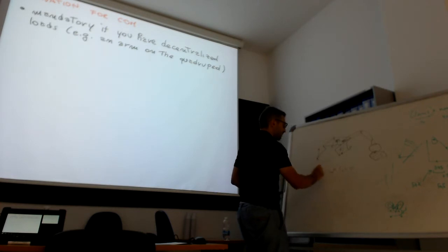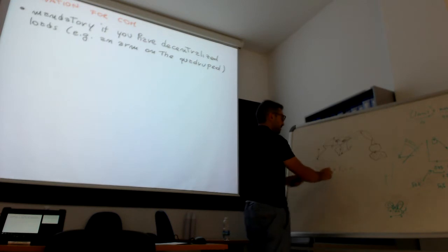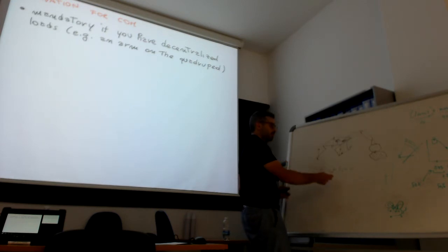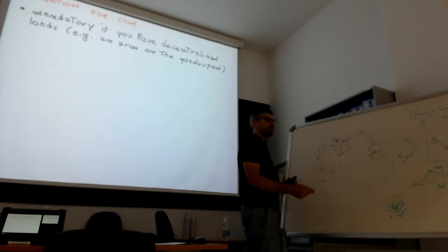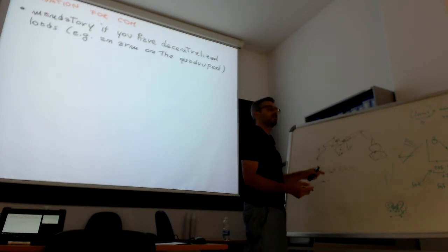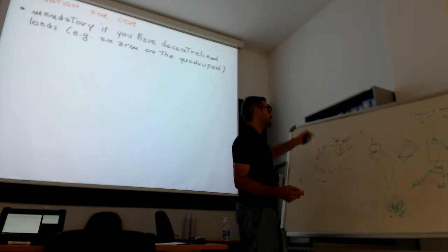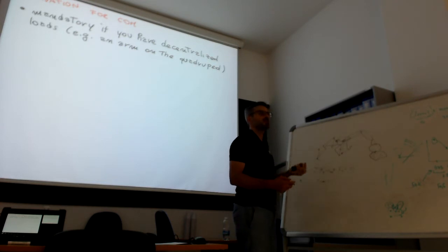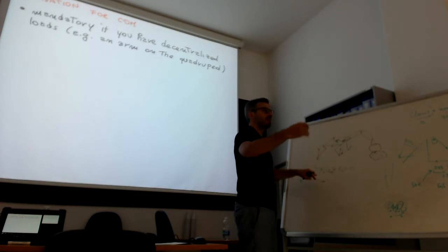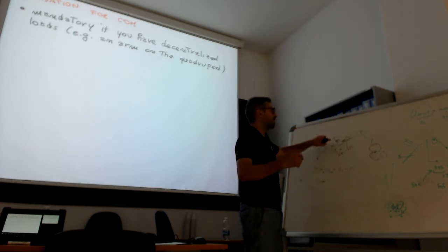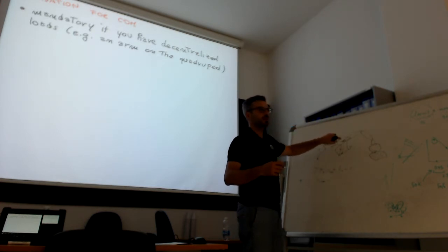This is F. And so if you elaborate on this equation, you can find an expression for an estimation of the center of mass, what the center of mass should be for these contact forces. Since doing an estimation in one step is noisy, I use this as a direction to update my actual estimation toward the real value.